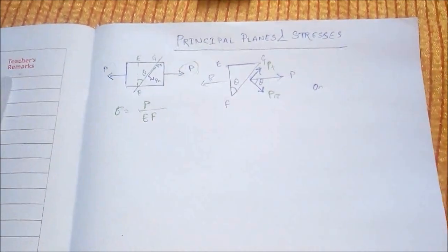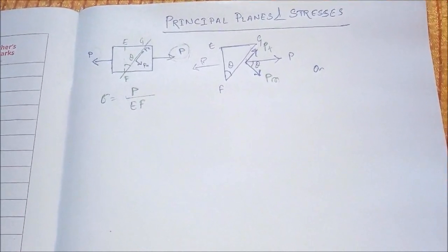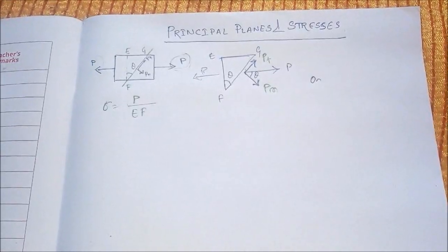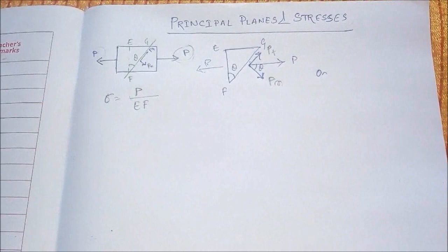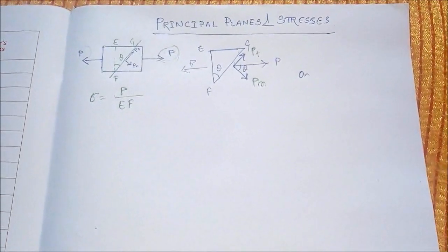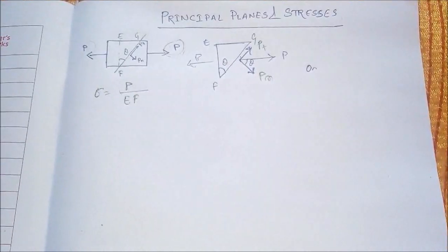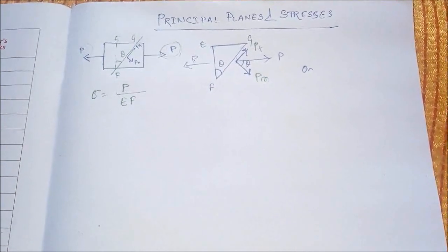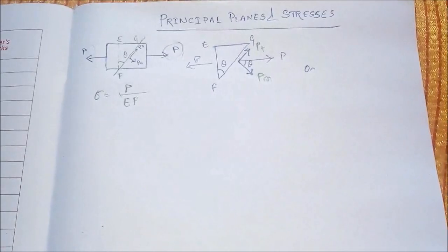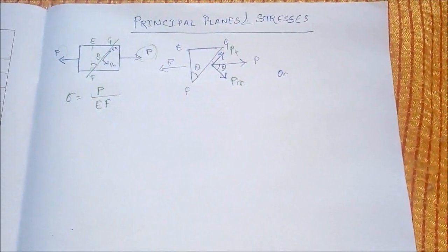Our today's lecture will be principal planes and stresses. What is a principal plane? Actually, if a body is in a strained condition, that means some forces have been applied on that body, then each and every plane on that body will be having some forces, basically normal force and shear force, the tangential forces on that plane.